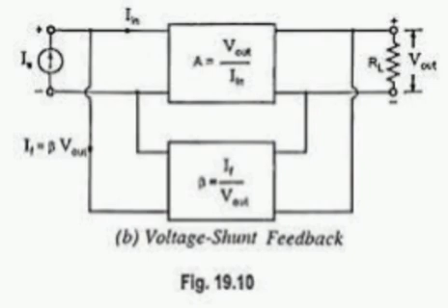Modulus of AVH equal to numerator part modulus of AVM, denominator part root of 1 plus f by fh whole square. F by fh plus 1 and separate. The angle of AVH equal to 180 degrees minus tan inverse of f by fh.